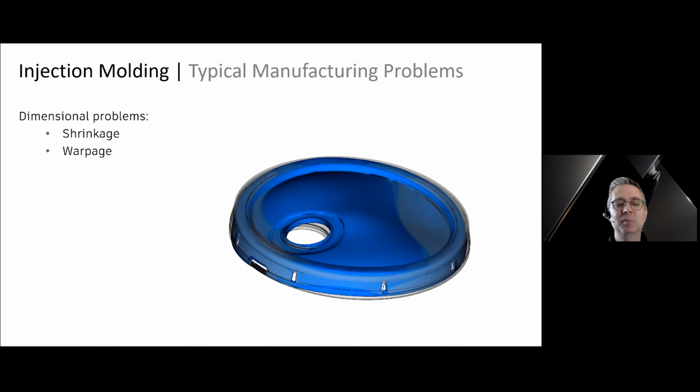For some parts that might not be a big deal, but for most parts there's an effect, because with plastic parts we design the features in, we design the function that we need. This example here would be a 5-gallon paint lid. If it doesn't fit on top very well and you accidentally knock the pail over, well, that's a bad day for your carpet, because the paint's going to leak out since the lid wasn't in the shape we intended, which allowed a leak.